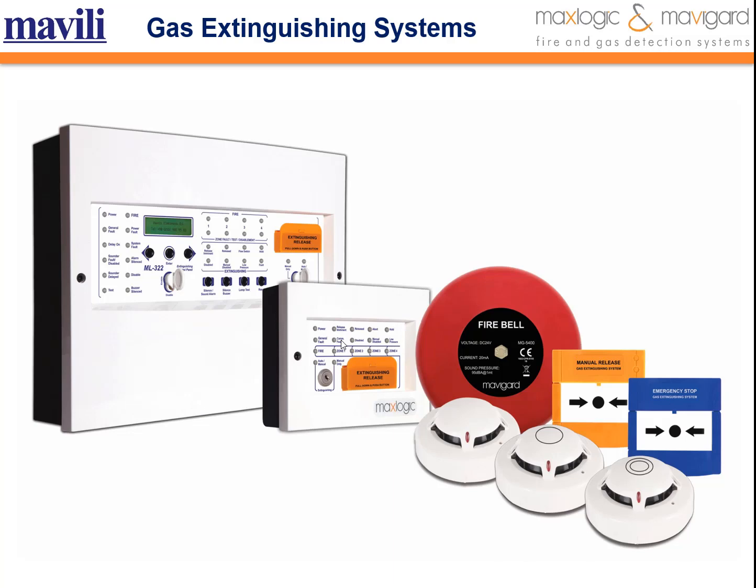These units work with 24-volt DC supply voltage and communicate with the fire extinguishing panel via the network card. Up to 8 extinguishing status indicator units can be connected to our extinguishing panel. These status indicator units control the continuity of communication with the fire extinguishing unit and inform the user with audible and visual warnings in case of communication failure.